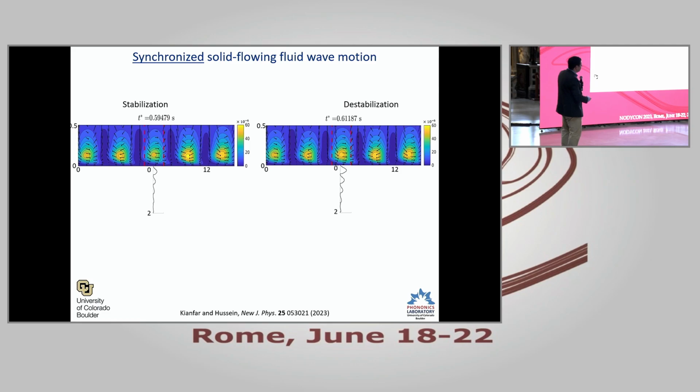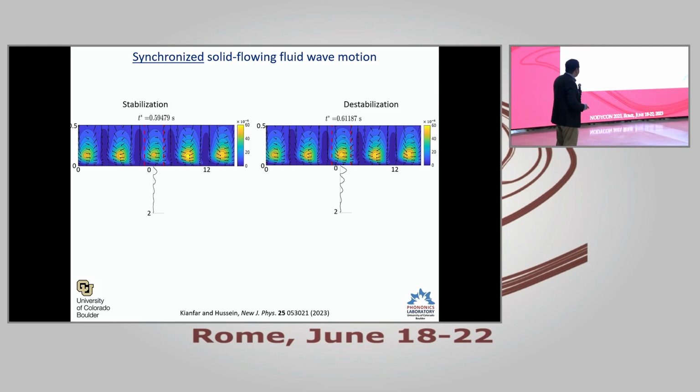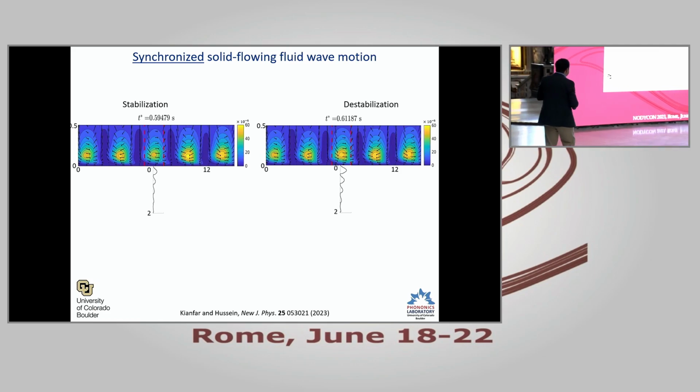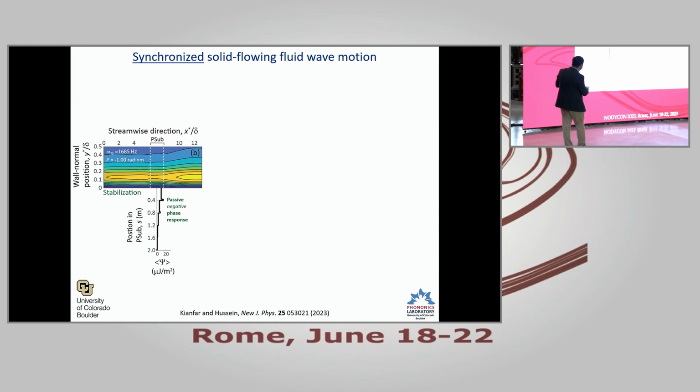And correspondingly, in the flow itself, it's minimal. Whereas in contrast, in the other case, it's high because that's an in-phase effect, which again corresponds to what I showed you before, that if you excite at a resonance, the structure will resonate. But what is interesting here is that this resonance will transmit through and impact the flow equally, just like it would with the structure.